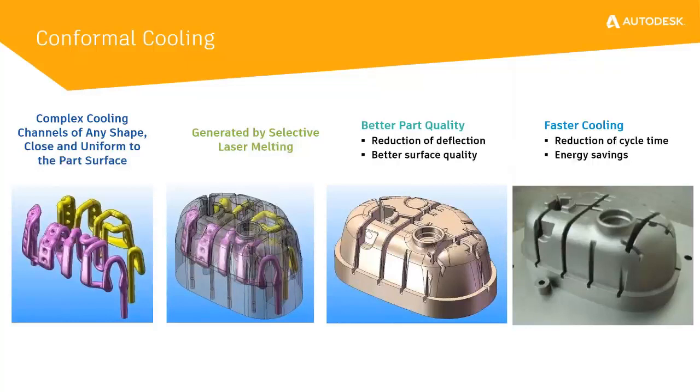Inserts created by additive manufacturing are typically more expensive than a traditional insert, and concerns of durability and maintenance are also issues. Leveraging Moldflow as a simulation tool is a great way to help when justifying the insert cost versus the expected cycle time savings. Moldflow can also show the additional part quality benefits, like the reduction in shear stress or warpage.